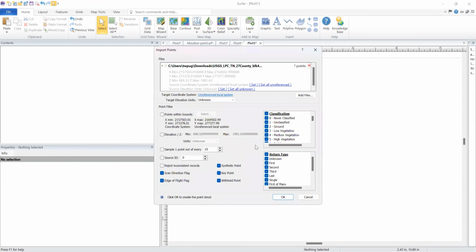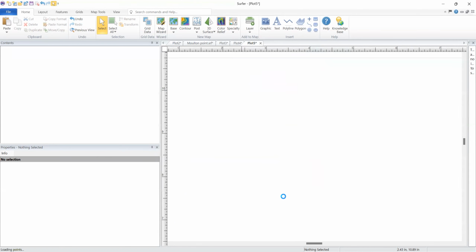And when you deal with it, you need to decide whether you want the whole thing. Do you want to be able to see all of the LiDAR data, or do you just want the ground surface? Okay, and I just want the ground surface. I just want to see what the terrain looks like. So you just click on classification and erase everything, and then you select on ground. If you do want vegetation, you would select on those two, and you just say okay.